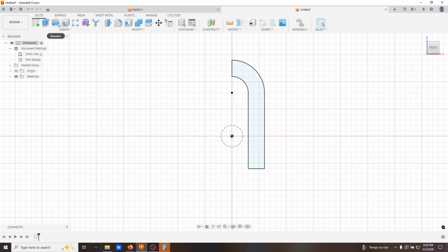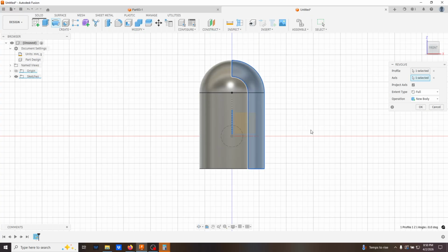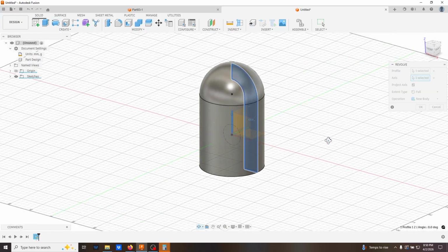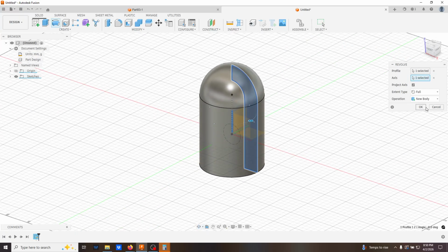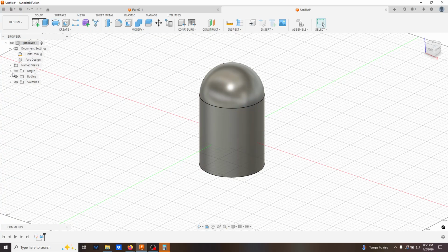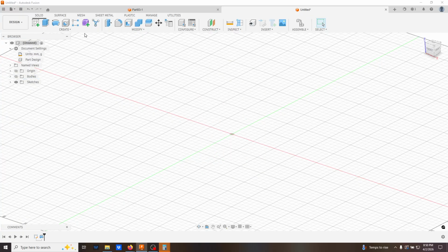So if you can organize your feature tree, you can throw reference geometry on different stuff. Let me actually just do this while I'm revolving it. What's nice is that if you make individual sketches, sometimes people think about making it really cluttered. You see how I have this here now. I'm just going to draw this and keep talking. When you put things on different sketches, and I'll have to make that visible right here so you can see it, I can create links between those sketches.